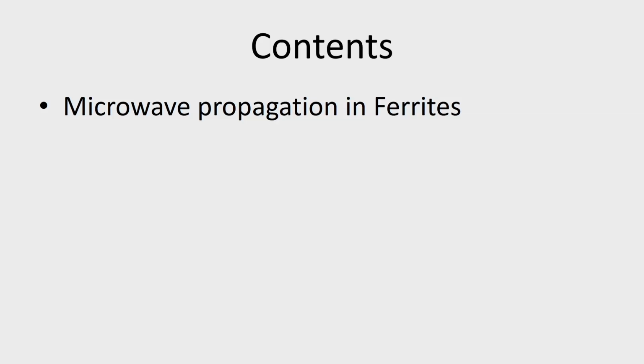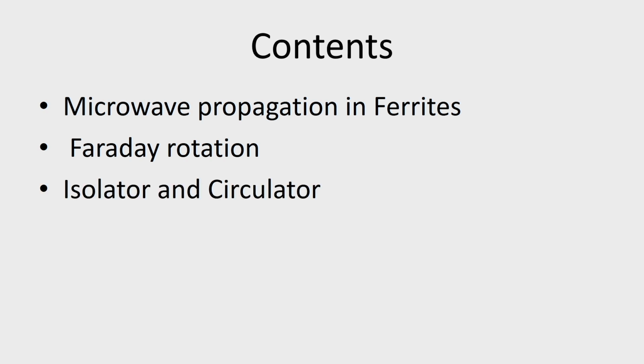We start a new module, ferrite devices. In this module, we are going to cover basics of microwave propagation in ferrites. Then we will discuss the concept of Faraday rotation, and then we will discuss how this Faraday rotation effect is utilized in designing devices called isolator and circulator.